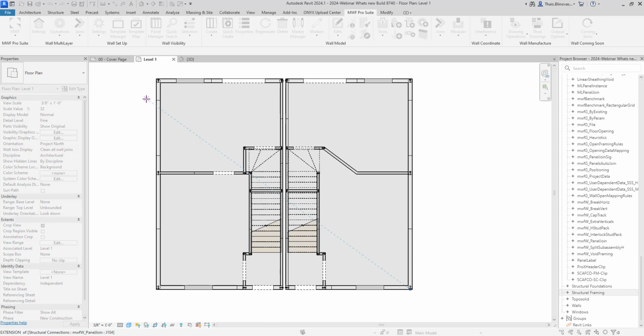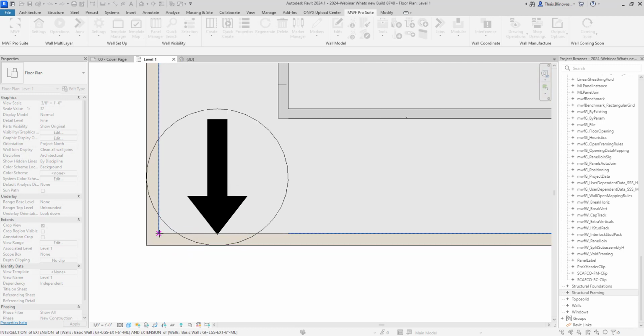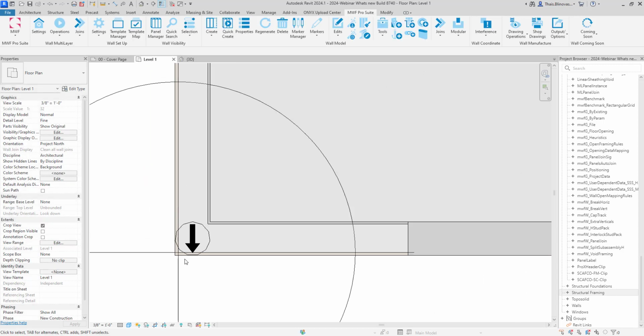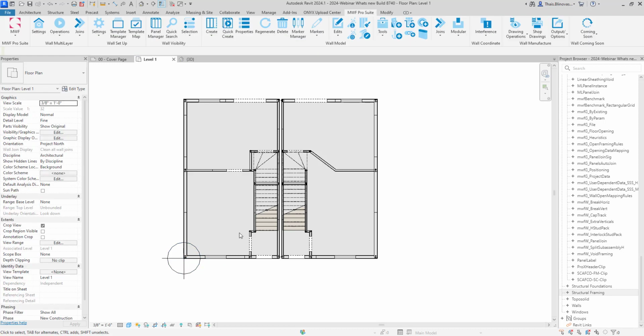Or if you don't have the Revit grids, you can just go ahead and click at any location. So let's say I go here to this corner and I select this location here, and once I click OK, I'm adding my benchmark there. If I select the benchmark, you will see under mark in your instance parameters, you have the name of that benchmark, BM10 in that case. And as I mentioned, that process also created automatically a new default template that is already associated to this benchmark.